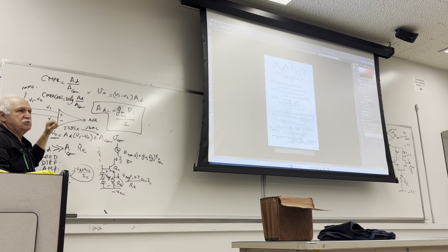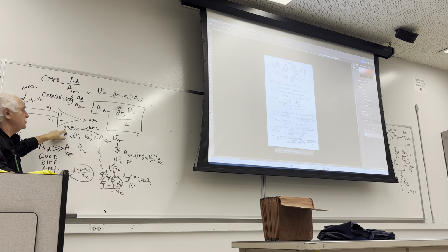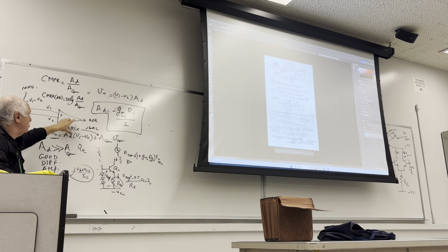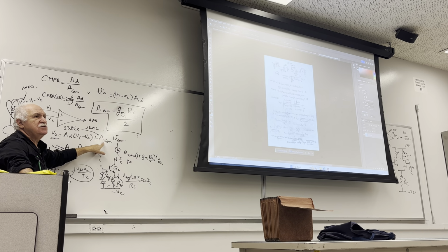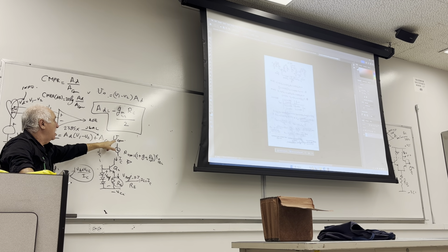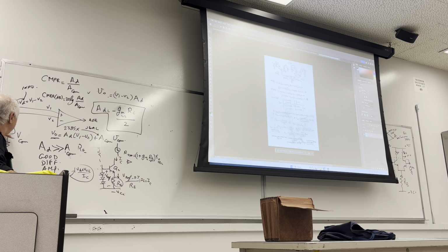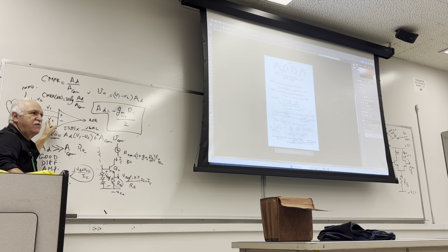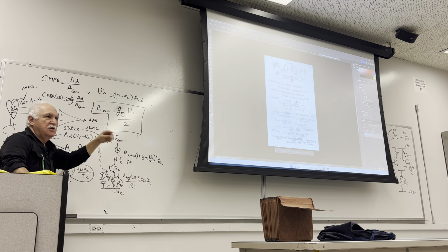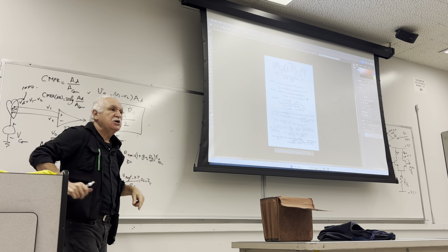1, 2, 3,000. So even if this was like a 1 millivolt signal, V1, V2, which is typically on the heart, 1 or 2 millivolt, you'll get gain of 2,000. So you will get 5 volt peak to peak heartbeats. Here, VCOM is only 1 time. So if you had like 1 volt interfering signal compared to that, it would amplify 1 time. You will get 1 volt. 1 volt against the 5. So this dominates over that one. So your signal will be much, much clearer.